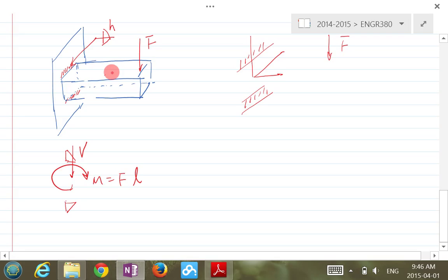But now you can imagine this. What does the M cause the weld group to do? It's going to cause it to rotate, right? But which axis is it going to rotate about? About this axis now, right? This axis. So that's essentially like, when we talk about the bar, you apply the F, you talk about the deflection, and the axis here, we call that what? Neutral axis, right? Yeah, neutral axis.